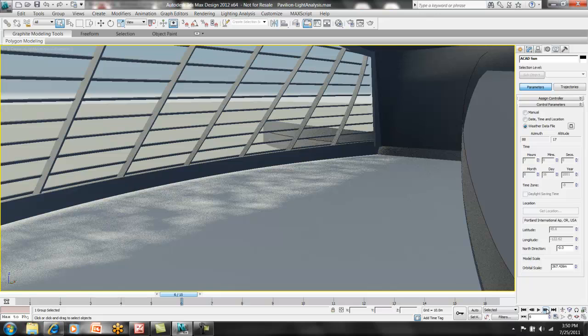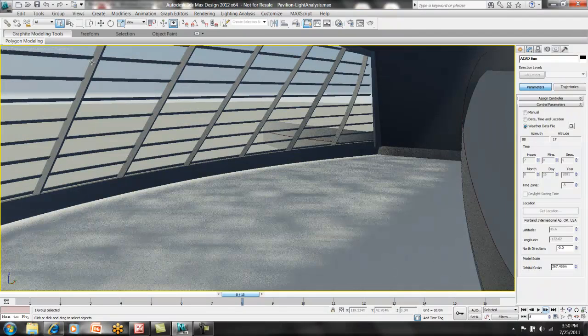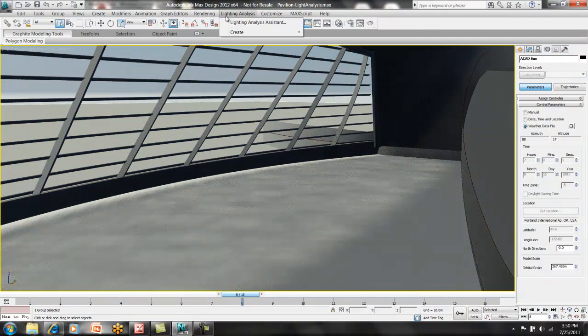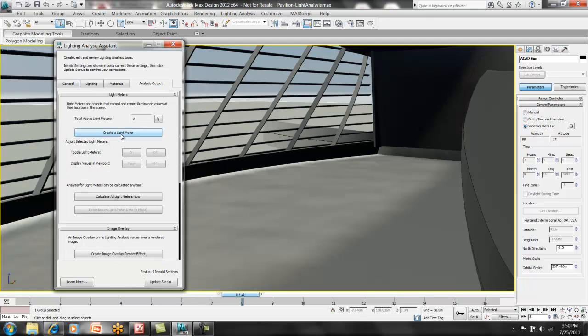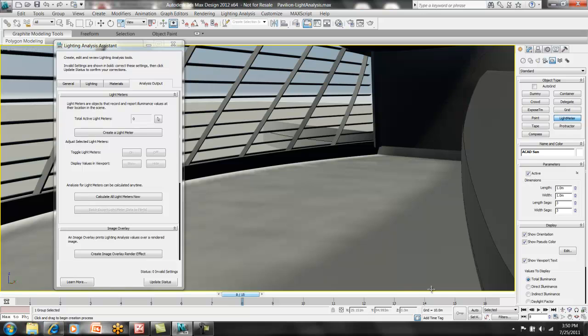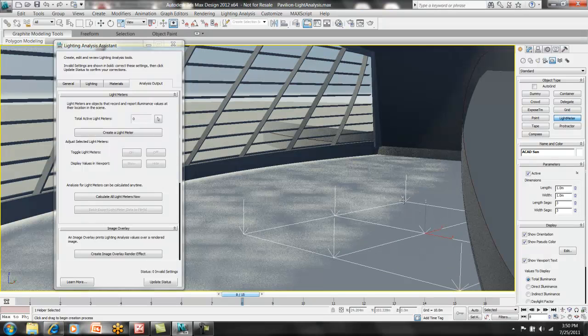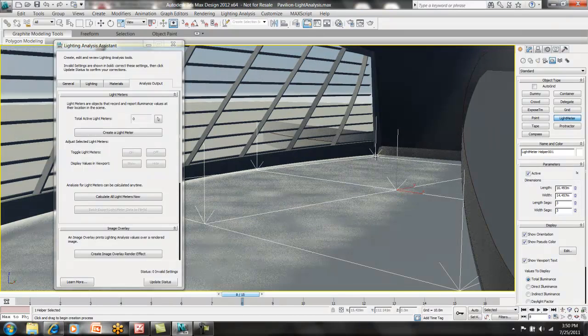Now so far we've just got a very good visual idea of what's happening. Is this going to be, like I said, architecturally pleasing for us? Is there going to be enough light in there? So next step is to take a look at the light analysis, and you can look and see I can do some lighting rendering, which we'll do later. But in this case, I'm just going to set up a new light meter, and I'm really more concerned about the floor, the lighting that's coming into this. Let's just call it an office. Is there going to be enough light, not enough light? Like I said, do we want to rotate around? Idea of the sunshades, not sunshades. We're going to do a pretty good job of kind of ruling some of those things out.